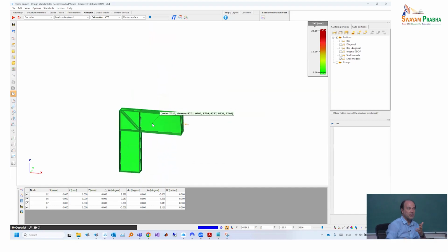Here the two effects are playing against each other, and finally they completely eliminate the warping deformation. If something like this comes into the beam, it can basically be considered a warping absorption device. So the two elements have opposite direction and the same size of behavior, and the two finally kill each other, and there will be zero.